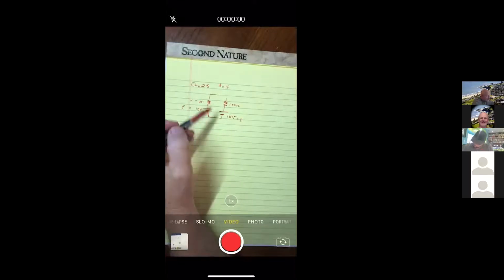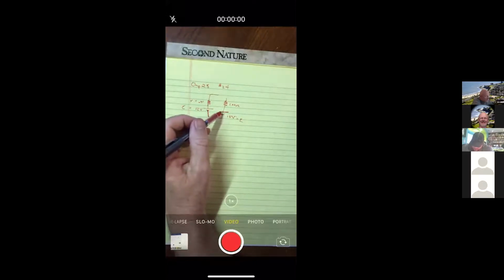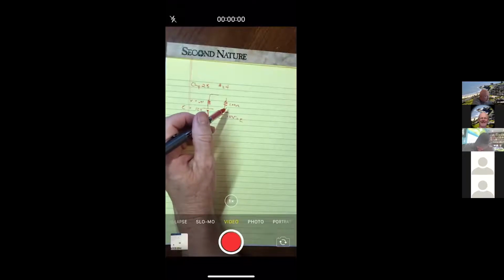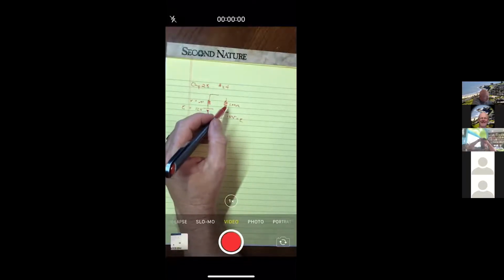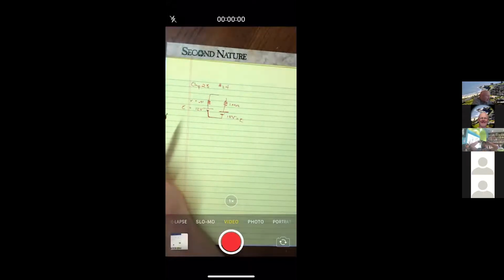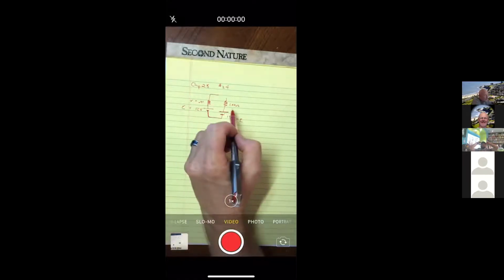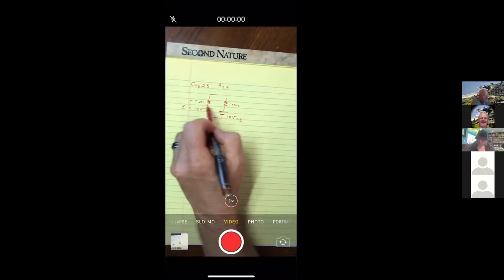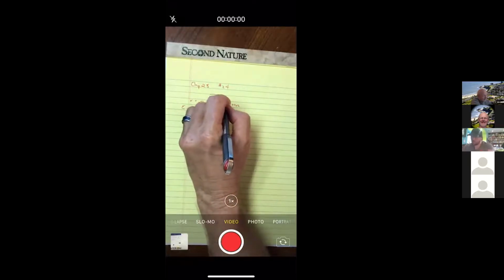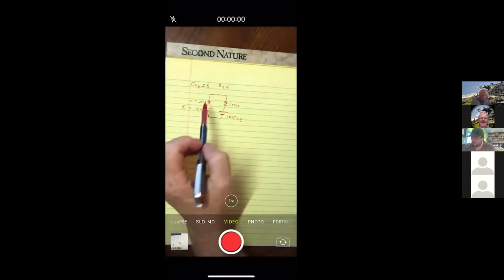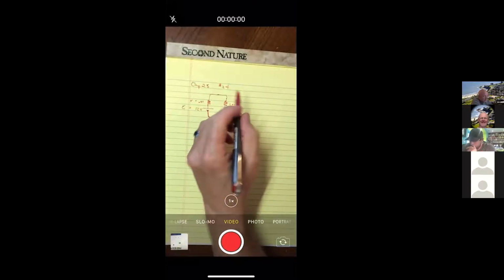And so in this case, probably what's happening is our concentration of sulfuric acid has dropped enough that we're not getting as much reaction here. And then, of course, given that there's less sulfuric acid, it's probably because we used up a lot of the sulfuric acid, and so a lot of the lead has become lead oxide and also water, both of which do not conduct as well as lead or sulfuric acid. So the internal resistance has gone up by a factor of 100. So this too is an internal resistance.